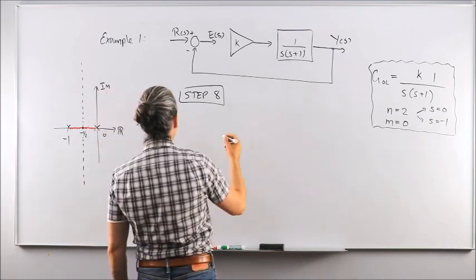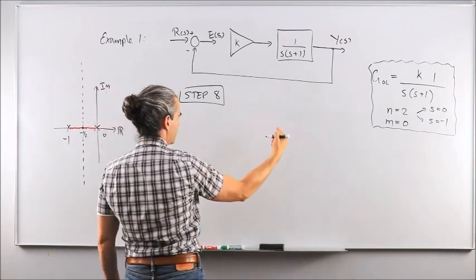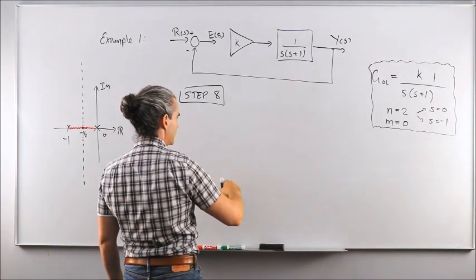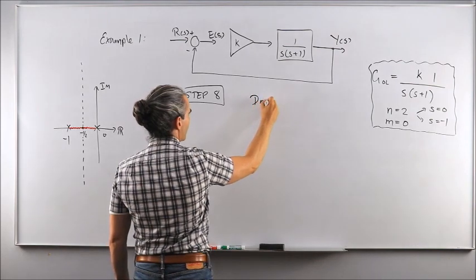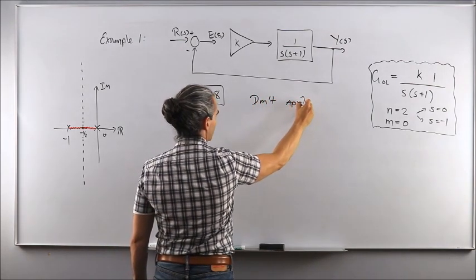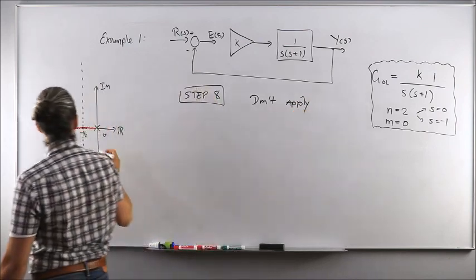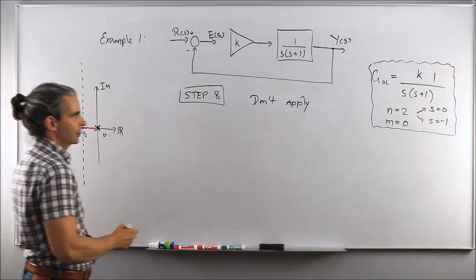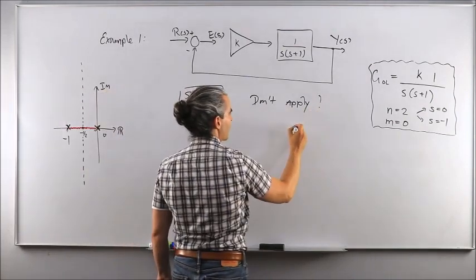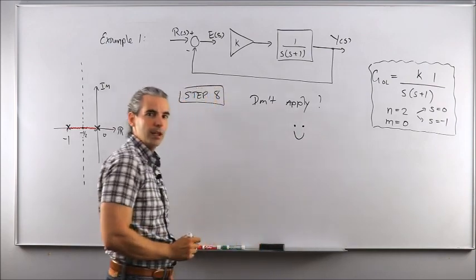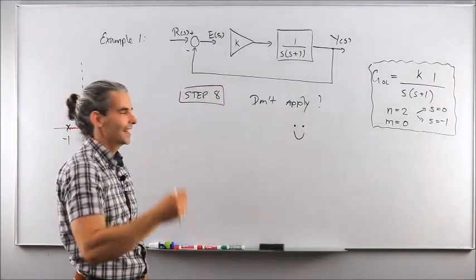But here, from complex conjugate poles all the way to complex conjugate zeros, we don't have any complex poles or zeros in our situation, right? All we have for the open loop transfer function are two real poles. So that equation doesn't apply. And that makes you super happy because you've just saved 5-10 minutes doing an exam. Yes.